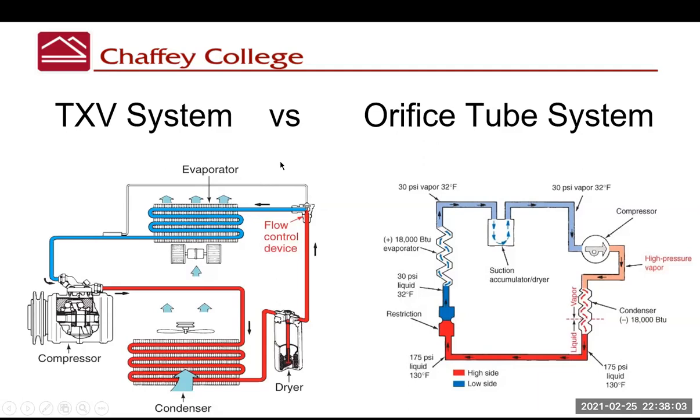That's how your air conditioning works at your house. At your house, you may have a condenser sitting outside on a piece of cement at the side of your house. And then inside where your heater is, they also have your evaporator. There's a compressor that you can hear running, pushing everything around. That compressor is usually outside with the condenser. So all of these components are in any type of refrigeration system.